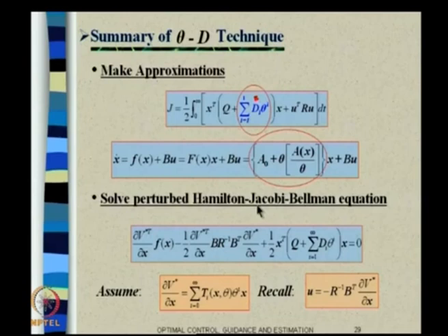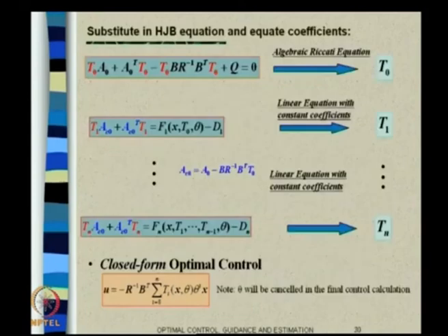Very quickly it converges actually. So, what it points out is one Riccati equation offline solution and about 4-5 Lyapunov equations which require online solution. And then these D1s are also appearing here. So, what the solution procedure tells is something like that.